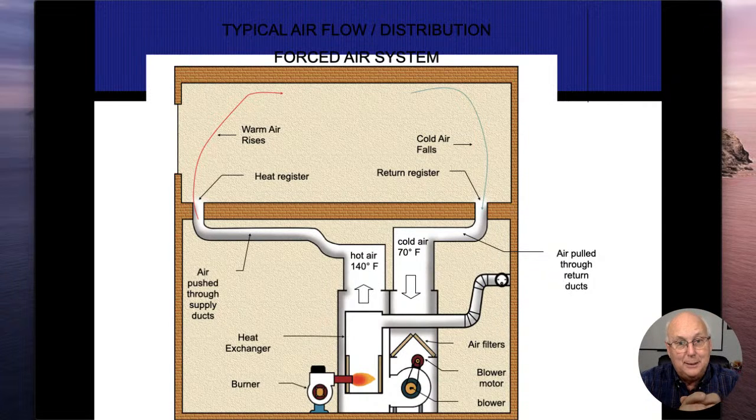All I'm saying is, in the design of these furnaces, we have multiple different safety features put into these things. The first one is going to be our fuel air mixture. If that oil burner is doing what it's supposed to be doing, or my gas burners or propane burners are tuned right, I'm going to produce very low levels of carbon monoxide. The carbon monoxide is what's going to harm a human being. All right, so that's safety feature number one. The heat exchanger itself, if that's intact and there's no cracks, openings, or anything else in there, then there's no way for those bad gases to pass over and get into my circulation air. Safety feature number two. And then the third one is going to be my air pressure differentials.